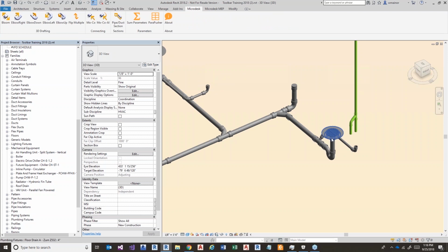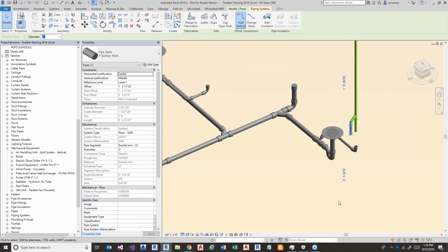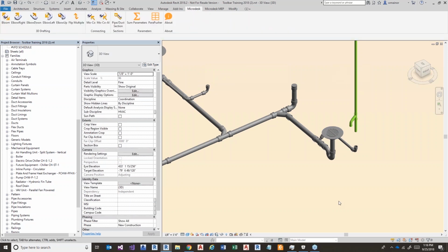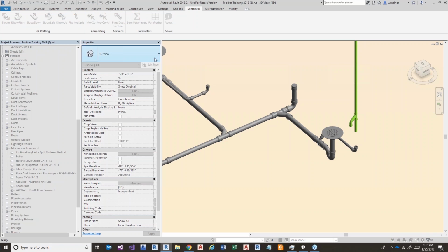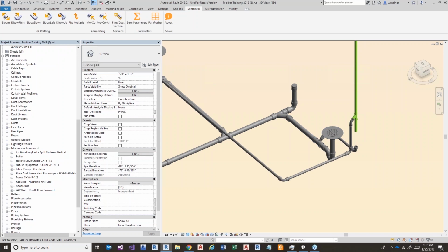No, let me do this the smart way. I'm going to delete the pipe that's coming off of the elbow down. Then I'll use the move connect command to click on that Husky O-clamp. That was part of my routing preference. Then I'm going to click on that little pipe branch that came up. And the command's going to do its best to move everything over.